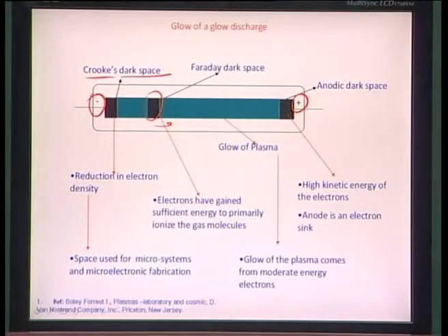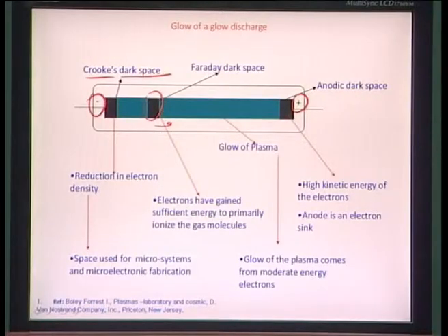So what happens near the cathode, the cathodic plate or the negative plate here, there is a formation of a dark space which was first identified by Dr. Crookes, and it is also known as the Crookes dark space. Essentially, as you know, the electrons which are rushing back towards the anode, especially the secondary electrons generated by the ionic impact, would almost always create fresh pairs of ions and electrons as they move in. So their energy is consumed in creating fresh pairs of ions and not the atomically excited states. The material that is created is basically losing a whole electron rather than retaining a high energy electron. Therefore there is a dearth of materials which would be giving glow in this particular region.